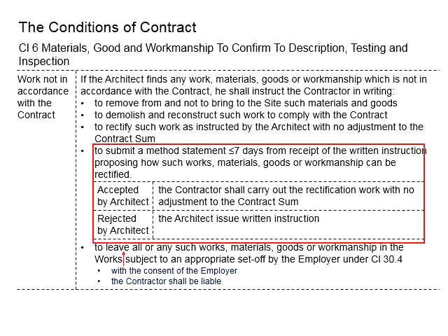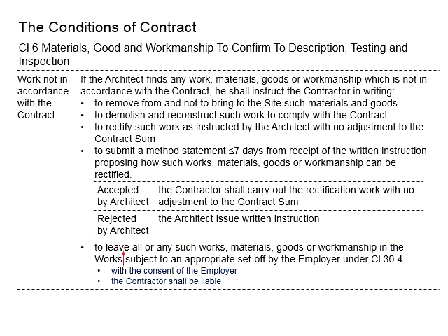Under these circumstances, when the method statement is being requested, that means the architect is giving flexibility to the contractor to decide the solutions as preferred by the contractor. This will require the approval or acceptance of the architect. If it does not satisfy, the architect will give instructions so that the rectification works will be in accordance to the methods given by the architect.